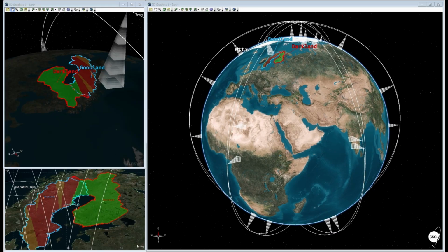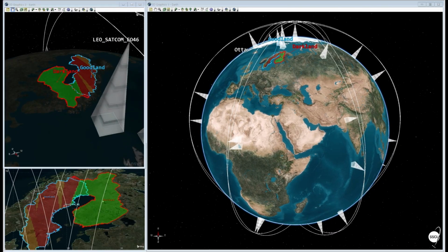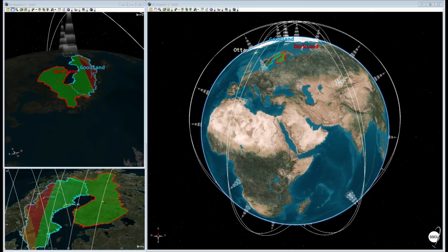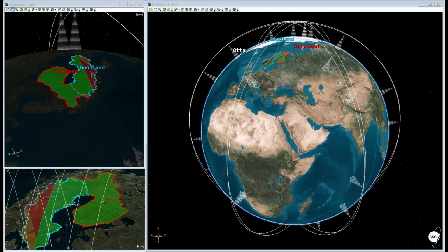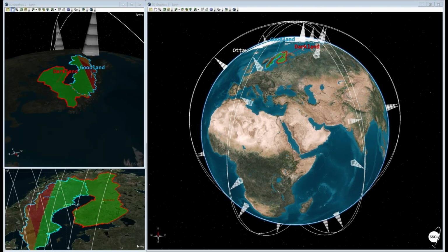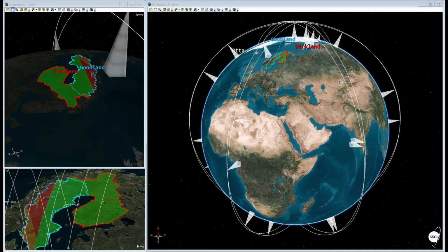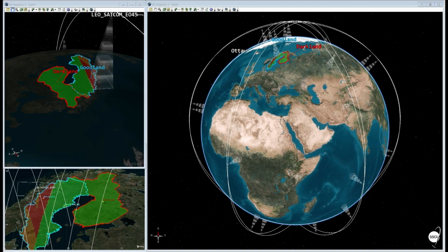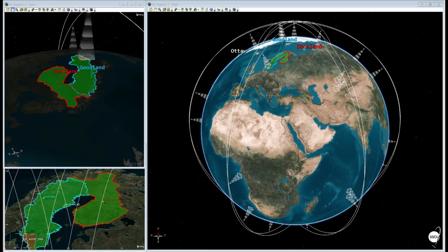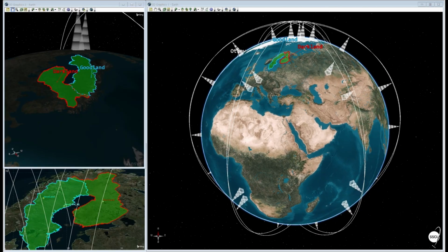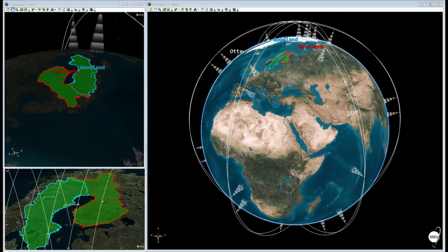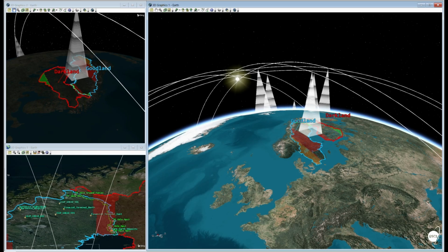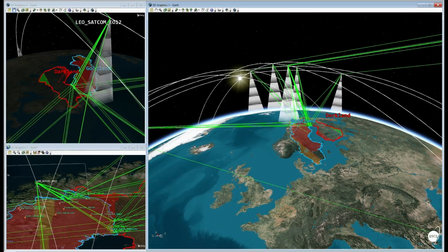Compared to Telesat's Lightspeed or SpaceX Starlink LEO constellations, this is quite a small number, but adequate enough to demonstrate LEO's capabilities. I have a coverage figure of merit overlay evaluating the revisit time. You can see that even with a fixed sensor, the average revisit time is very frequent and can be near continuous with enough satellites. Coverage on the ground is much smaller and is constantly changing.